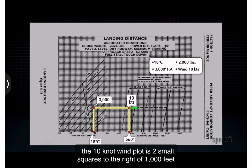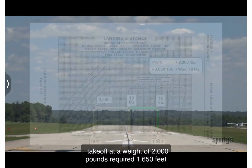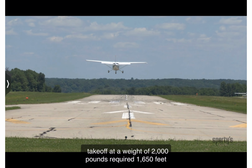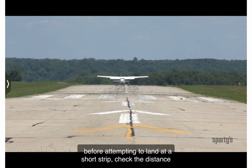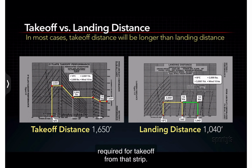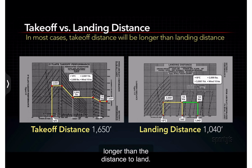The 10-knot wind plot is 2 small squares to the right of 1,000 feet, making the total distance to land over a 50-foot barrier 1,040 feet. Takeoff at a weight of 2,000 pounds required 1,650 feet to clear the same 50-foot barrier, which only required 1,040 feet to land over. Before attempting to land at a short strip, check the distance required for takeoff from that strip. For virtually all airplanes, the distance needed for takeoff is longer than the distance to land.